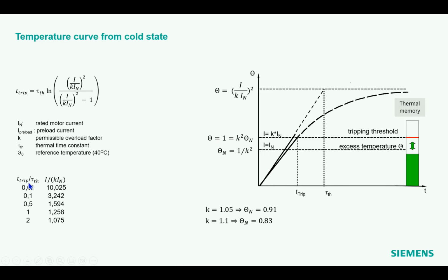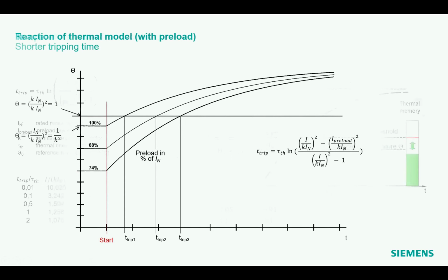And this is rather practical because if the tau is relatively long, then I can cut off my testing time. So instead of injecting 1.5 times current and waiting for 20 minutes, I get here maybe in 90 seconds the result when I use that. Just to mention, I think this is a nice handy thing which I put here on the slide.